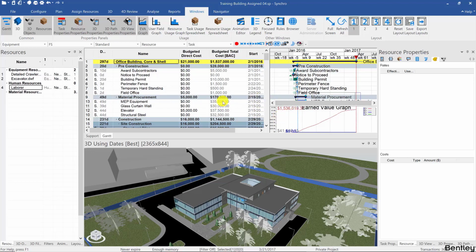Of course, you can capture a baseline, you can change the tasks, see how the cash flow changes. Now, we haven't really talked about, once I assigned this, we assumed 1 unit per day per task. We haven't really talked about how to change these and how to efficiently use model properties to do that. We'll do that in the next video, which will focus more on resource loading. But for now, we just need to know that there's time-based and fixed cost, as well as task-based and resource-based costs.